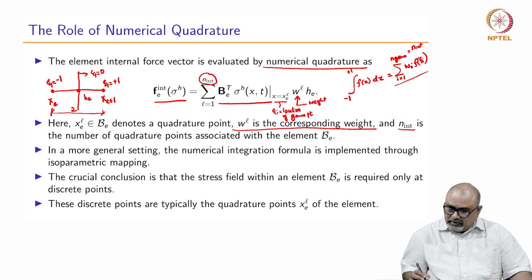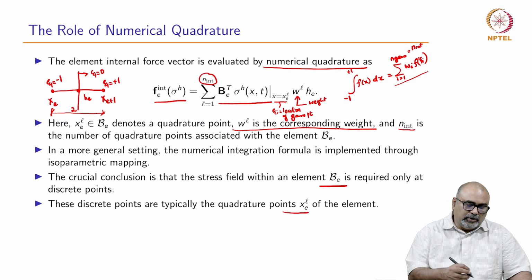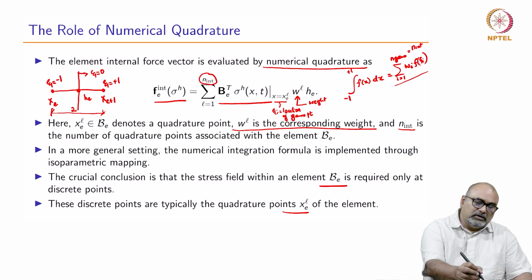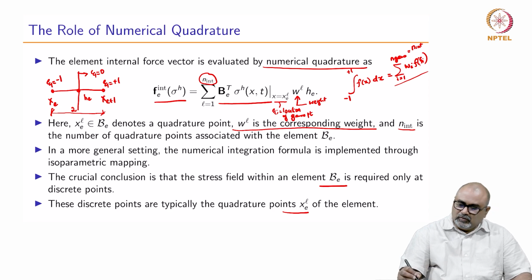So, the stress field inside the element can thus be calculated, and the quadrature points can be specified, and one can have 1 point quadrature rule, 2 point quadrature rule, or n point quadrature rule to evaluate integrals of this form which are going from minus 1 to plus 1.